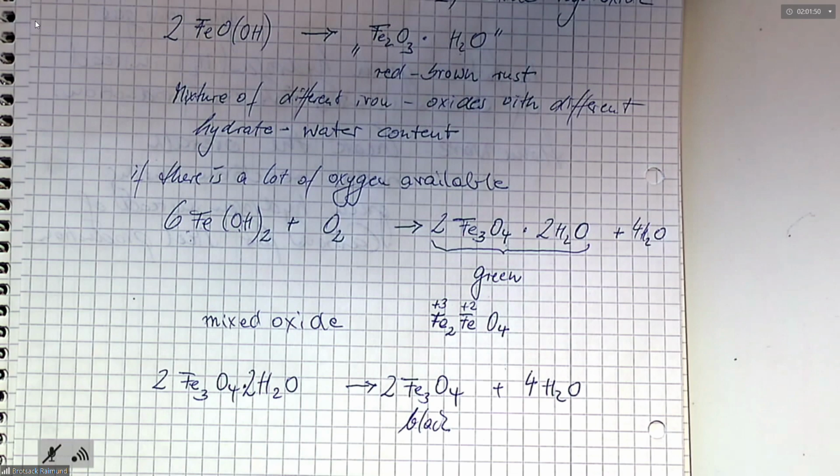If you have direct contact with water on the metal, you have a high conductivity, because water has a high conductivity, so electrons and other charges like hydroxide ions or protons can move quite quickly when you have water directly in the environment. That means the corrosion process can be enhanced in speed when it's very humid or directly wet.